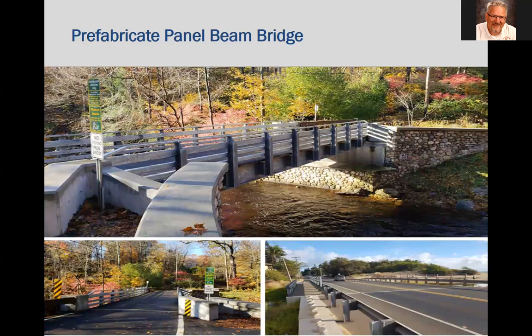The Acro prefabricated panel bridges provide a simple design, quick installation, a long-lasting life expectancy while meeting and even exceeding AASHTO load and design requirements. The Bouquet Street Bridge shown here used an orthotropic deck and steel guardrails, but the standard panel design can also use timber decking or a cast-in-place concrete deck and concrete jersey-type barriers.